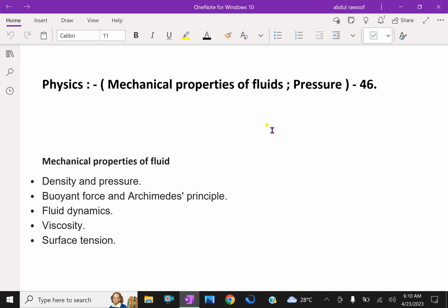We have learned in the previous lessons that normally the volume of solids can be changed by stress. The volume of solid, liquid or a gas depends on the stress or pressure acting on it. When we talk about fixed volume of solid or liquid, we mean its volume under atmospheric pressure. The difference between gases and solids or liquids is that for solids or liquids, the change in volume due to change of external pressure is rather small. In other words, solids and liquids have much lower compressibility as compared to gases.